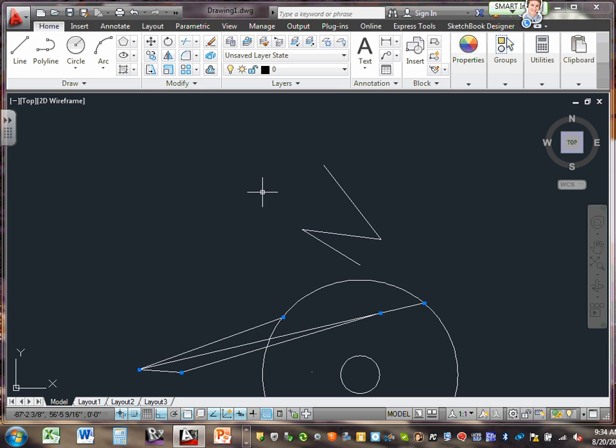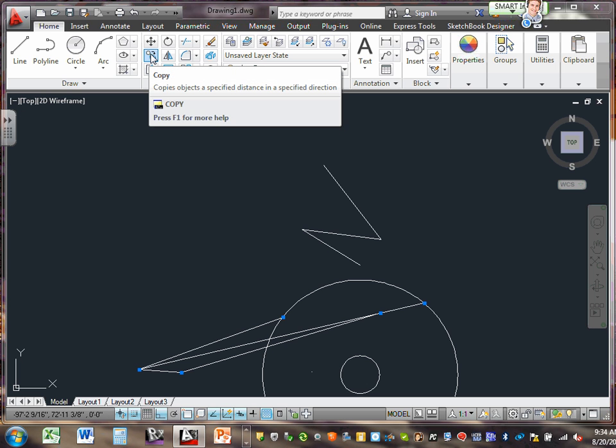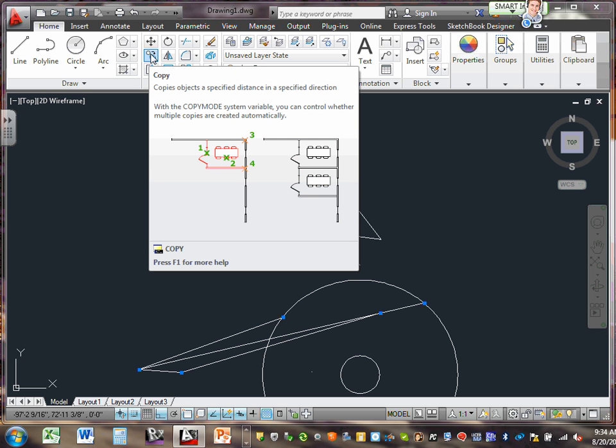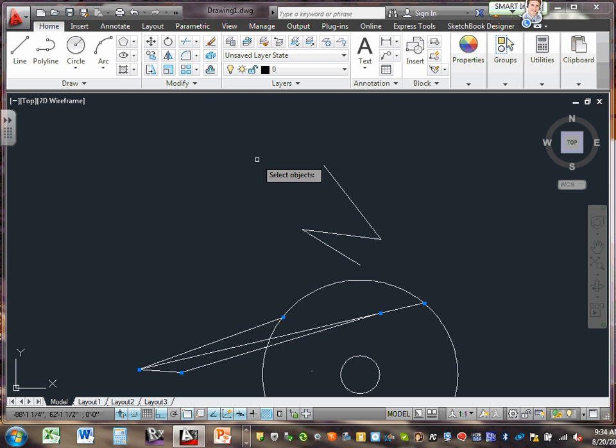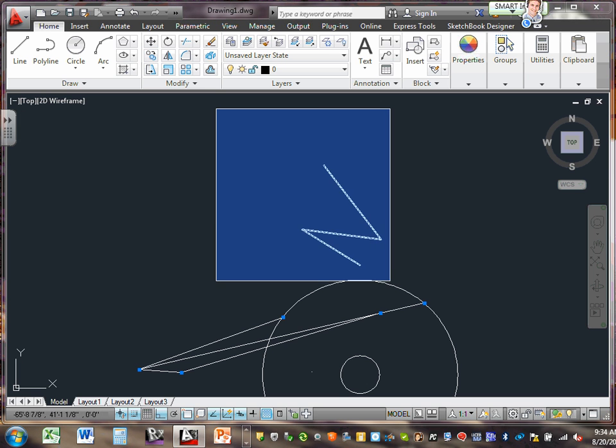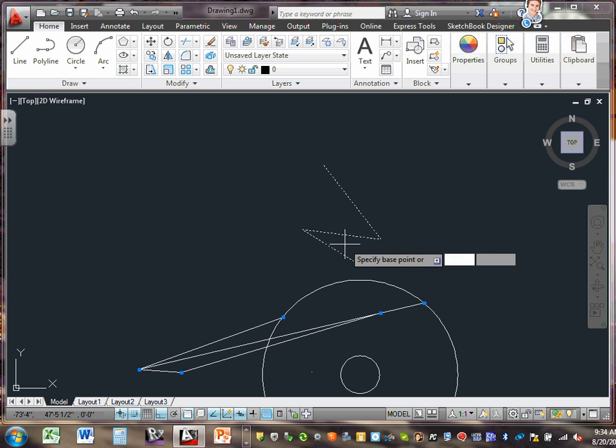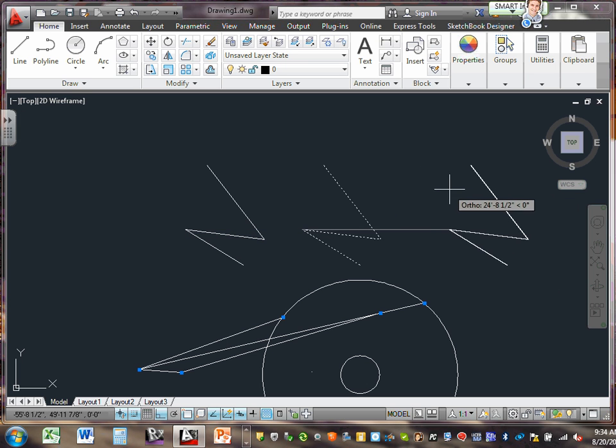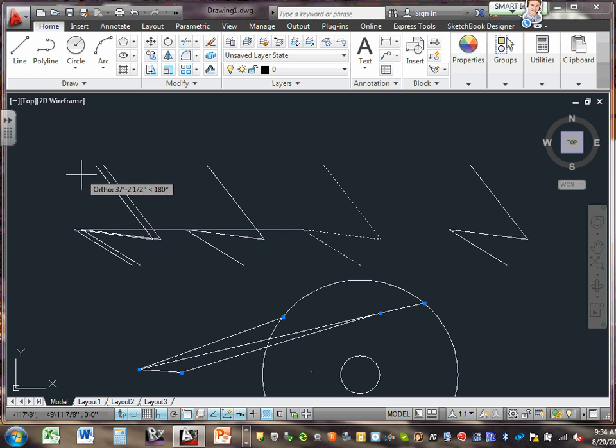Okay, we did the snap objects. We did the rotation. Copy. Can you guys see where it says copy here? Do me a favor. I'm picking a certain function that comes handy. Click on copy. Now, if you have a receptacle and you really want to copy that receptacle to another wall, that's how we copy. So first of all, pick the copy, highlight the thing that you want to copy, right click, pick the point that you copy it from, and off it goes. Can you guys see that? Now I have an identical, and you keep going and going until you hit what? Escape or enter. I copied this one 3 times.